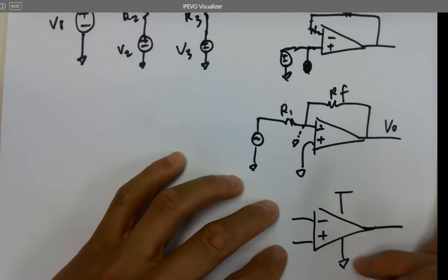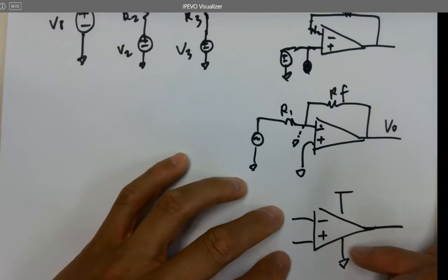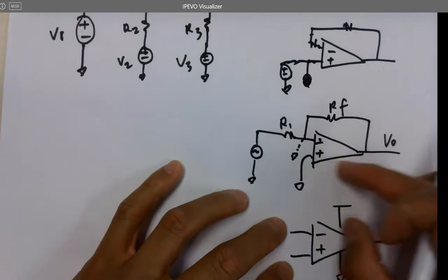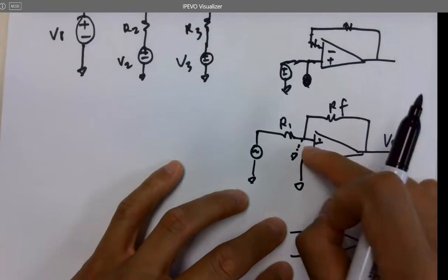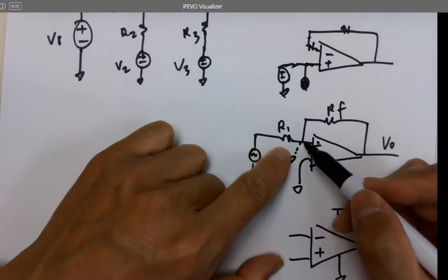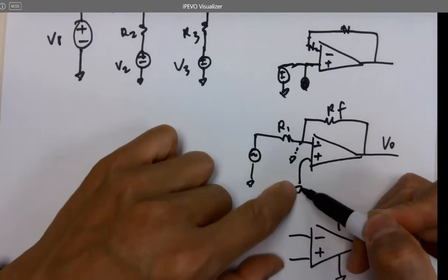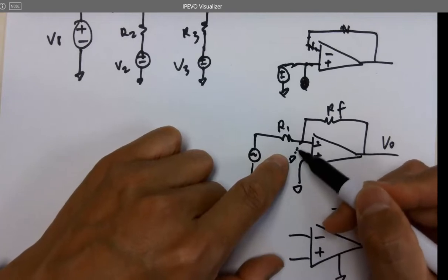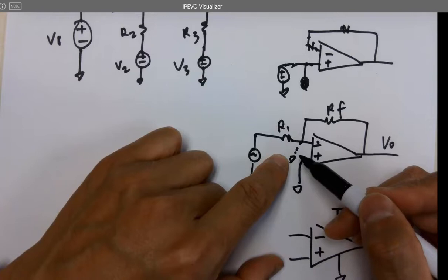It can be an interview question, right? Because this is everywhere. And just don't mention if you know how to use it. You don't even know why they're equal. So whenever someone asks you why, if you ground the non-inverting pin, this node here equals 0, just simply say because of negative feedback. So where is the negative feedback? It's over here.